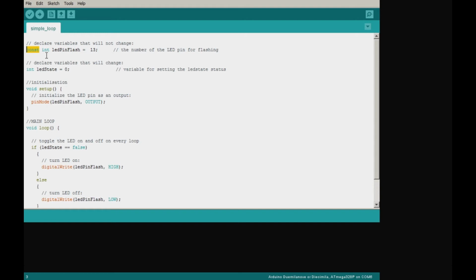In a normal situation, in most compilers, as I say, it's not always like this, but most of the time it will put this value into a ROM location in the microcontroller and not into a RAM location, because generally you tend to have more ROM space than you do RAM space, and compilers tend to know this, and so it's better to put them in the ROM location, because we don't need to change it.